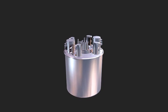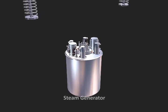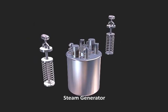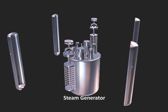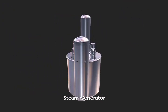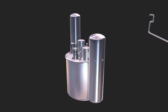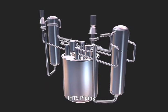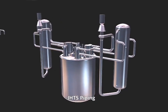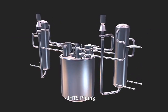The next view is the constitution of the Intermediate Heat Transport System, called IHTS. The IHTS consists of the steam generator, mechanical sodium pump, and the connected sodium pipings. A compact piping arrangement achieved in this system benefits the maintenance and repair work, and this feature also makes the system economical.